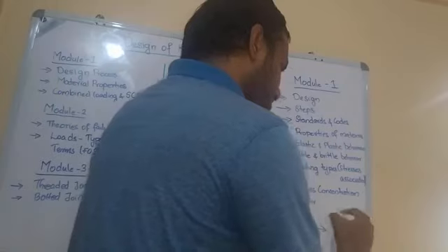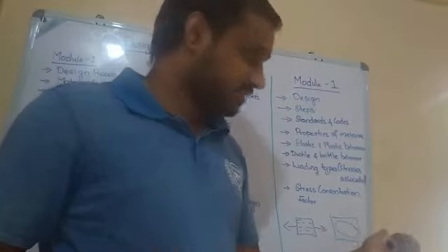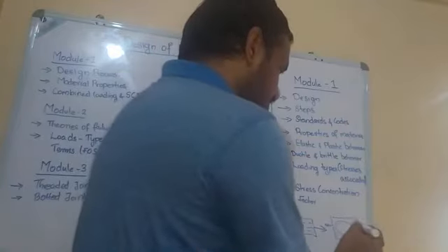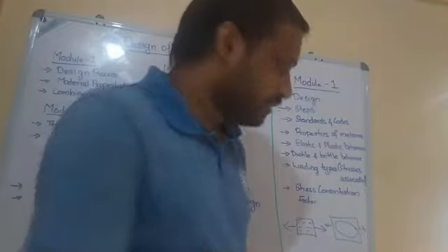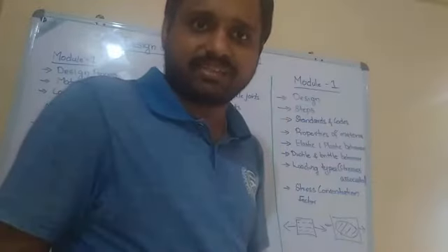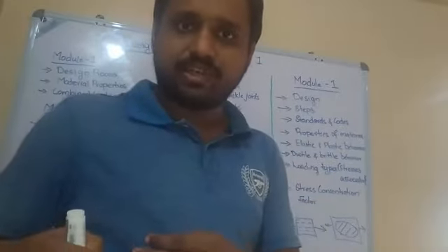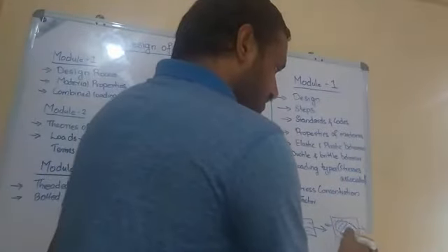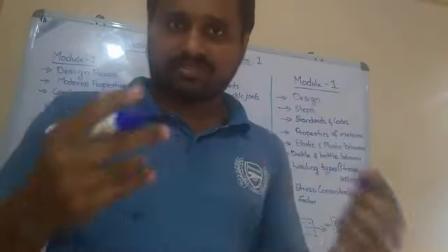But what happens if you are keeping a hole on it? This you have already studied in your advanced mechanics of solids. So what happens if the same force is applied? The stress will not be even, because here you don't have material, the area is reduced. What happens if the area is reduced? The stresses increase, because stress is force by area. So if area is reduced, stress should increase, right? So there will be stresses generating towards this hole. That is known as stress concentration.